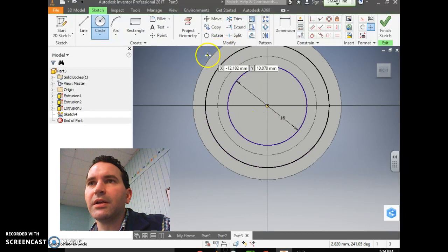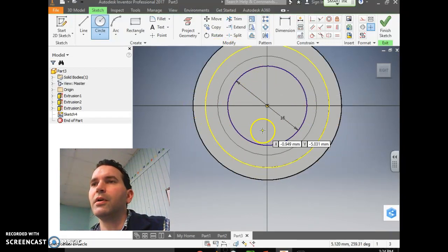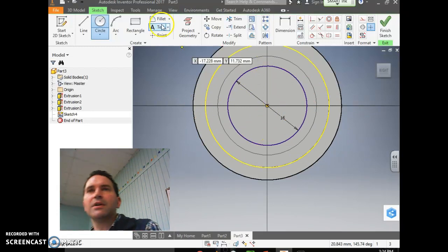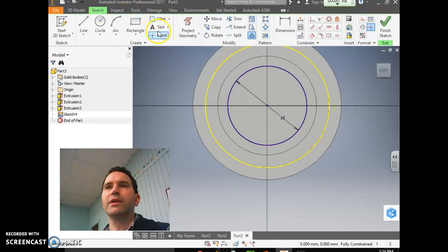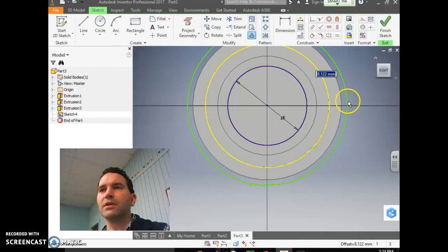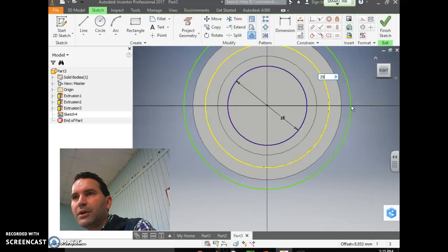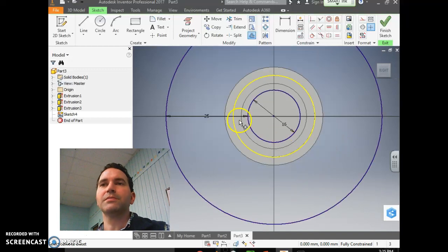I'm going to zoom in on this. We had one way on the outside, 2, 3, 4. Now we're 16 in diameter in millimeters. Now we're going to click offset again. So sketch, offset. That's under sketch, modify, offset. So we click the circle that we just clicked earlier. Now we're going to offset that 25 millimeters. 16 plus 25, I guess. Alright.